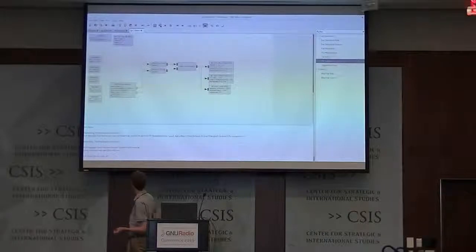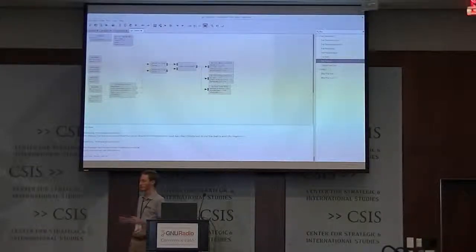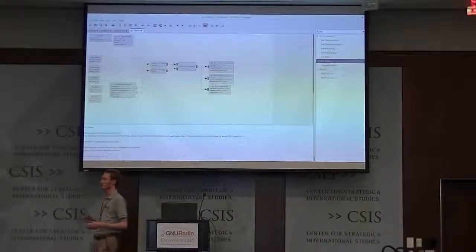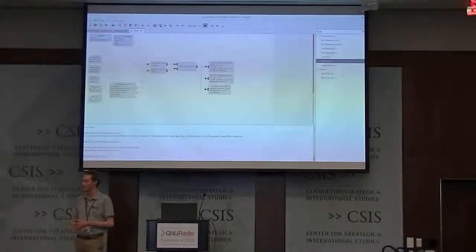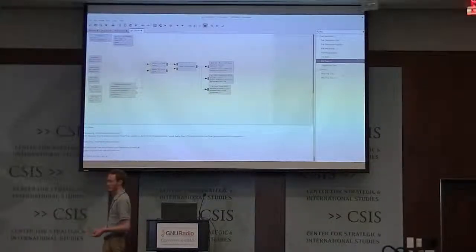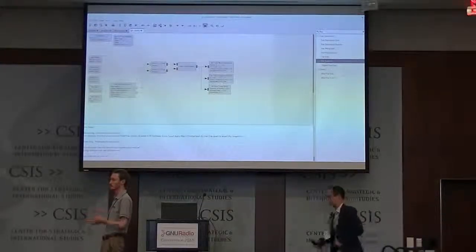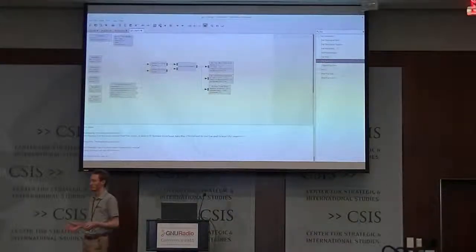If I understood correctly, you're asking if we can have multiple source blocks at the same time in one program. That's possible if you're using the network backend. If you use the local backend, then you can only have one application using the device at the same time. But in this case, there is the server running on the target board, and we just enter the IP address, and that would work as if two clients connect at the same time to the server, so they will get the same data from the server.